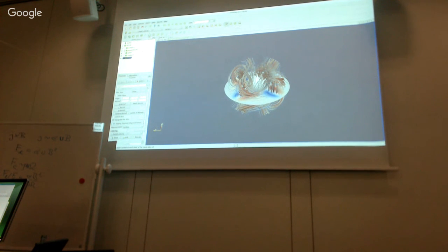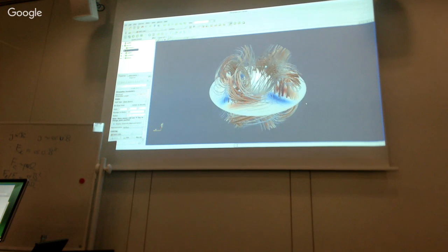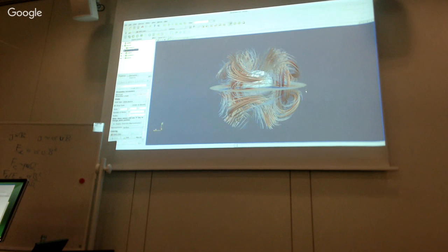Yeah, with the streamlines, you have to make sure that you use the number. The only tricky thing with the streamlines is where you locate your seeds, and this is controlled by this radius here. Yes, but a point click is defined differently. That doesn't matter. Okay, that's not difficult. And then the maximum length is that important? Well, you can play with that in case it doesn't look very good, but usually I leave the default. Position 1.5, and then I say apply, and nothing appears.